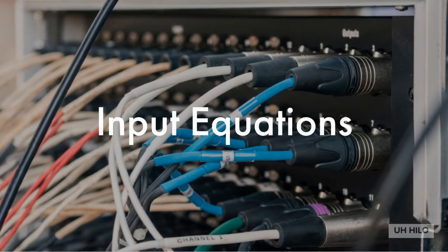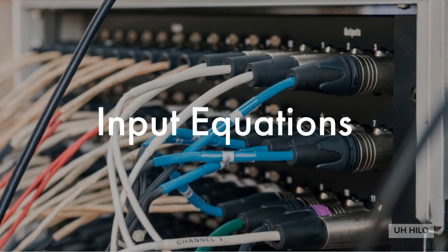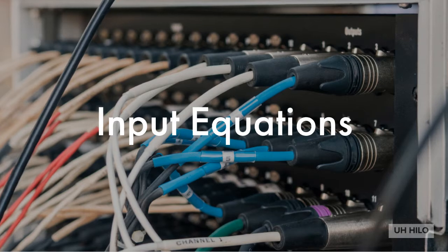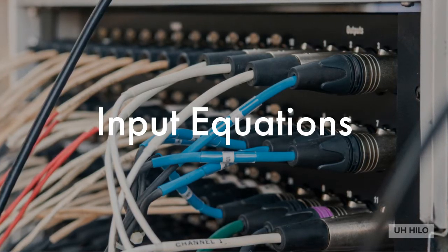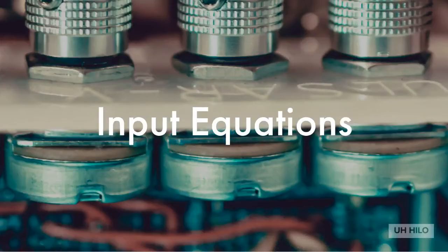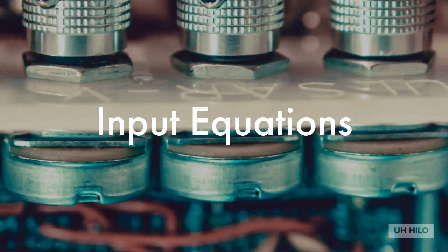The logic diagram of a sequential circuit consists of flip-flops and usually combinational gates. The type of flip-flops used and a list of Boolean functions for the combinational circuit provide all the information needed to draw the logic diagram of the sequential circuit. We need to pay special attention to the part of the combinational circuit that generates the signals for the inputs of the flip-flops. These can be described by flip-flop input equations.